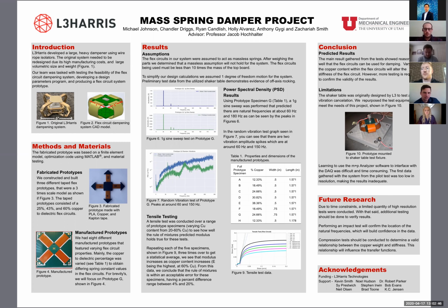We then found a formula on Science Direct using Castigliano's theorem, where we model these springs as semicircles and apply a force load on the top and get a spring constant, K value, to understand the dynamic response of our system to ultimately predict the natural frequency of our system. From there, we did a 2D FEA Abaqus model to see how well Castigliano's theorem matched what we were doing. And we found a verification of the highest difference being 0.05% between Castigliano's and our 2D FEA. So we used that to calculate our K values in the Matlab code.